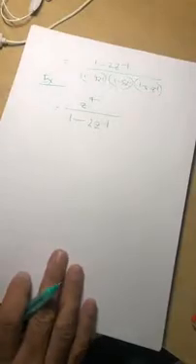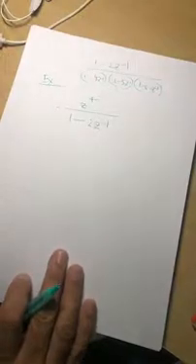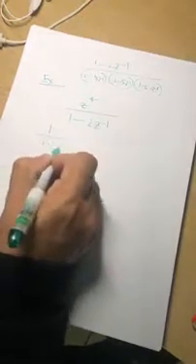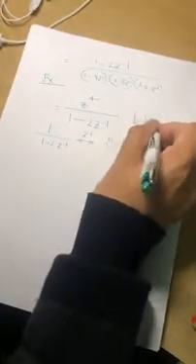So now we know that usually this is how, or sometimes you may need to use properties. Like if I have already solved this, but if it says z to the 4 over 1 minus 2z inverse, this is an example. Here you know that you need to apply the delay property. First you say 1 over 1 minus 2z inverse, and the inverse Z transform is 2 to the n u of n, especially if I tell you that the magnitude of Z is greater than 2.